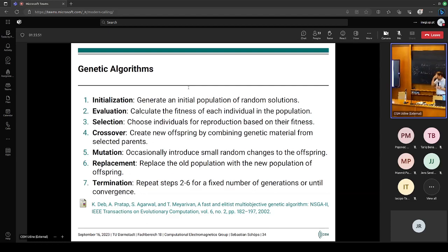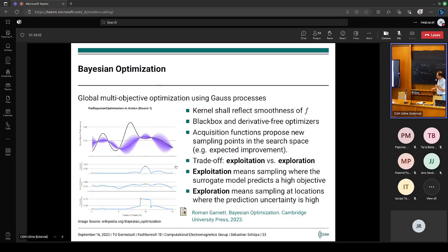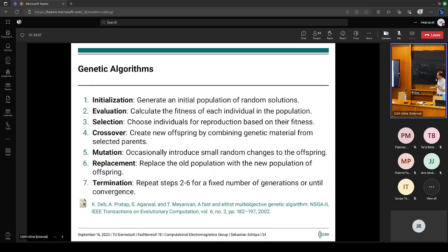What we have done there is mainly to create a response surface first, and then we let the swarm or genetic algorithm work on that response surface. This has a significant drawback compared to this approach, because, you remember I explained this exploration phase. If you apply this algorithm just to a response surface, there is no way to explore anything, right? If you have missed some things in the parameter space, you will never recover it. But nonetheless, if you have many constraints, if you have complex problems, this is very attractive. It just works.